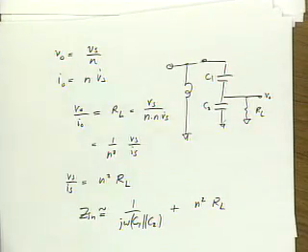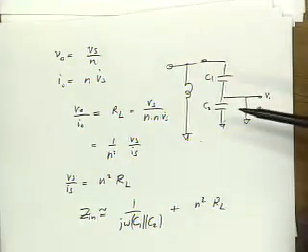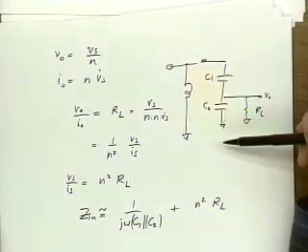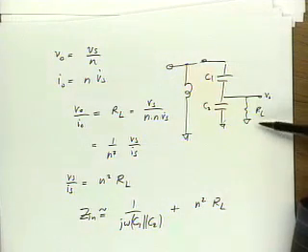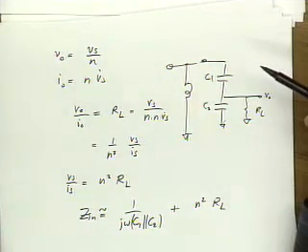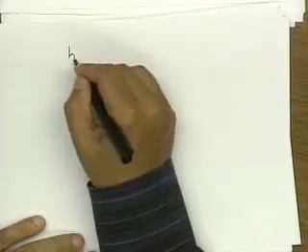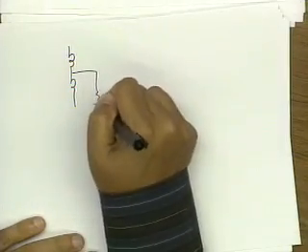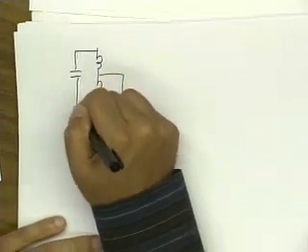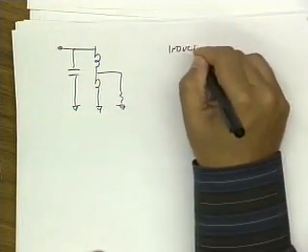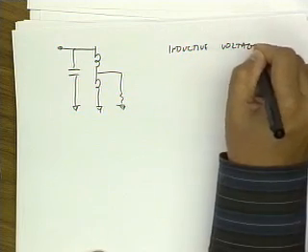It's particularly nice for integrated circuits because it just involves using capacitors and possibly an inductor if we don't like this capacitive part to load us down. And it lets us go from, let's say, small resistance to a large resistance or vice versa. Okay. Now I can do the same thing with inductors. I can have an inductive divider and then use a capacitor to tune out the inductive part. Same basic idea. So this is called an inductive voltage divider.